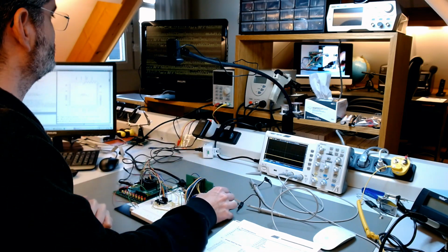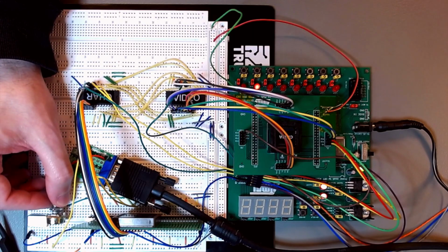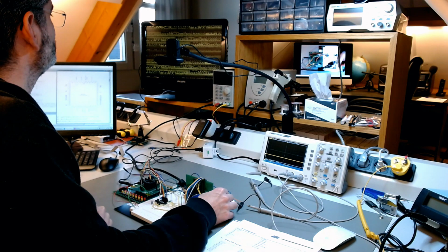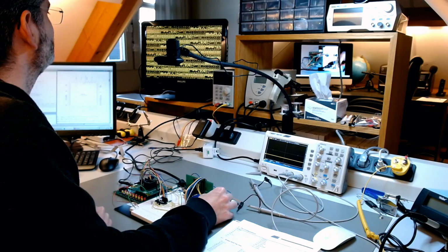Let's play around with the potentiometer to see what we can do. This only gets worse. Here's the image I'm actually getting. As I just mentioned, there's one obvious problem. The characters are mirrored. That's not a big deal. I know where this is coming from. I'm just loading the byte into the shift register in the wrong order. I'll explain this in a moment and we can fix it.